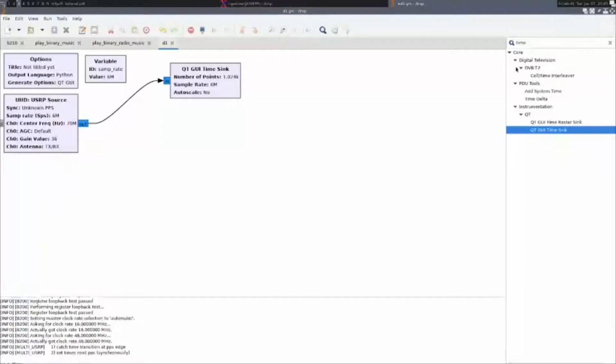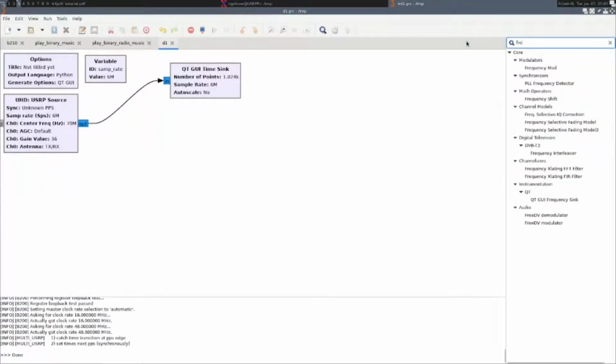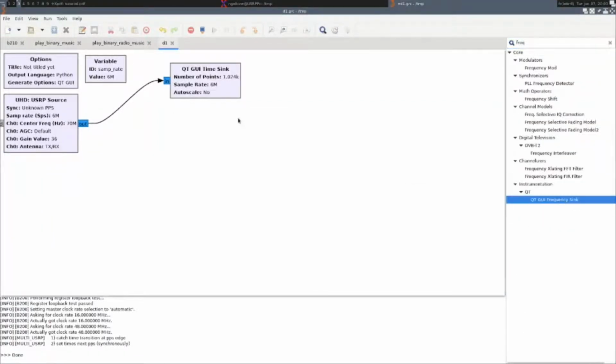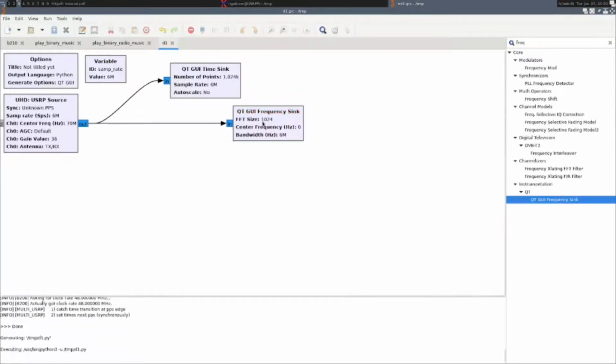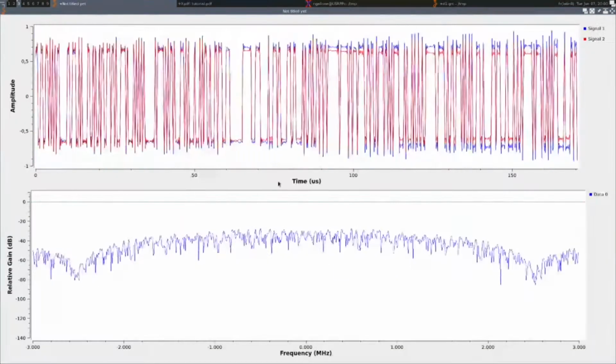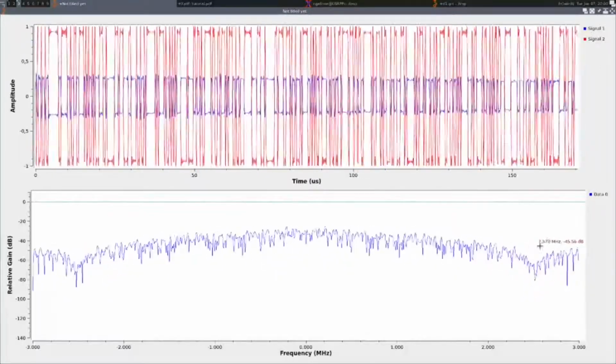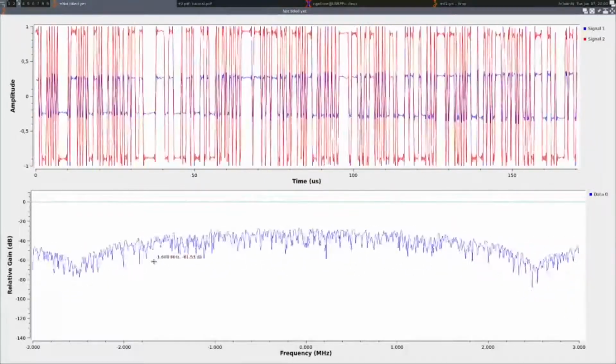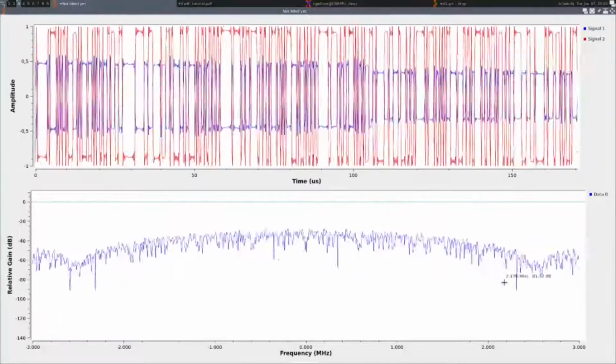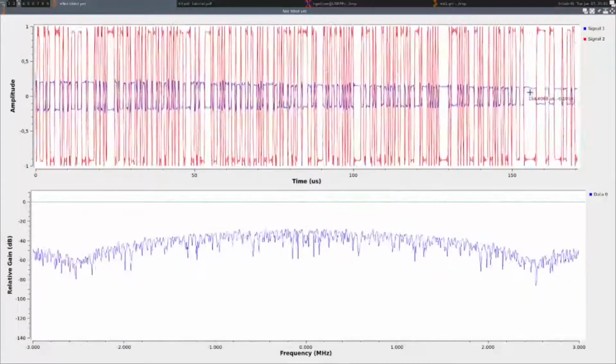So if we look in the frequency domain, if we want to have a look at the spectrum analyzer, we can see that actually the carrier at 70 megahertz has been spread by the modulation, and this spectrum spreading will occupy the full bandwidth from -2.5 to +2.5. The two notches here are at the data rate, and we've spread the energy over the whole bandwidth.